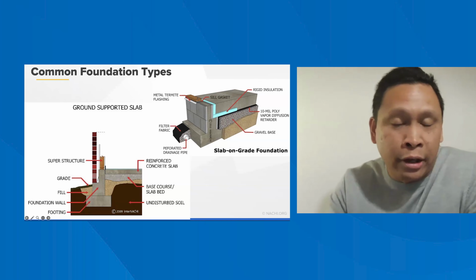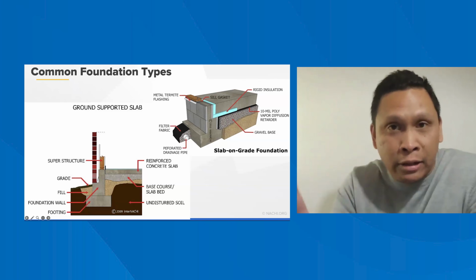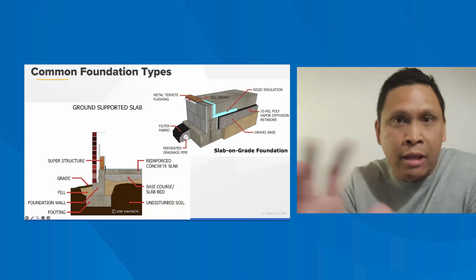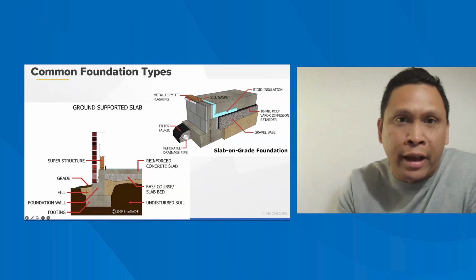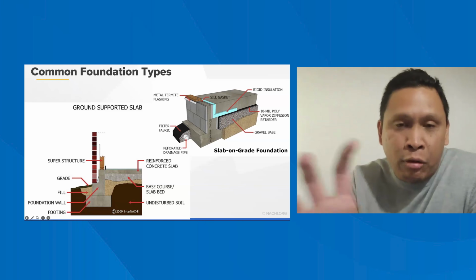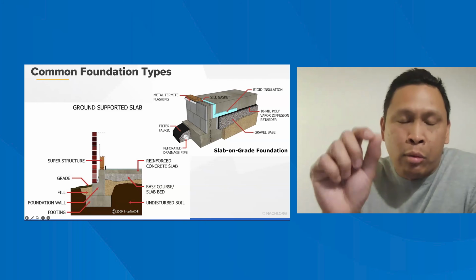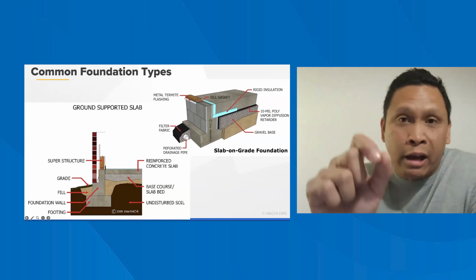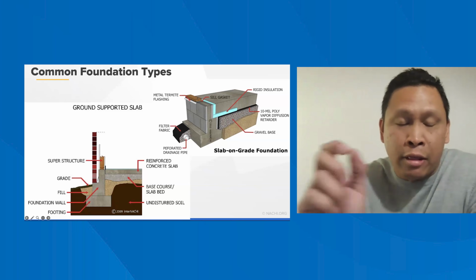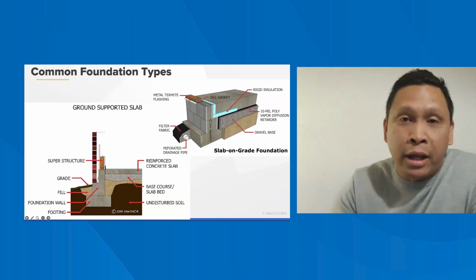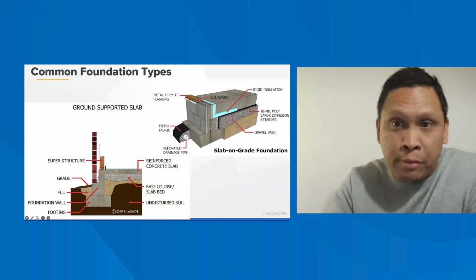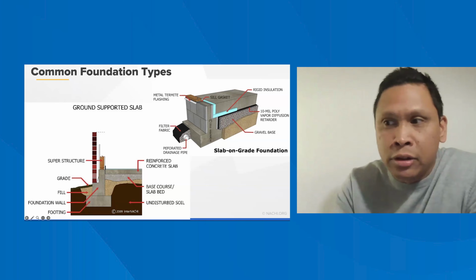So normal, right? Joist hangers. And they've got two sides to the hanger system. So you've got the left side and then the right side. So left face, right face. And typically the way that the contractors will do it is they will tack one nail or install one nail on each side of the face, and then they'll do that for all the hangers to make sure that the hangers are level first before they go in and install the other nails.